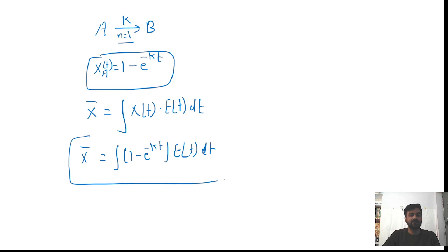The residence time distribution plot will be given, and I will show you in the next lecture with the help of one example. After that you will get to know, and the integral will be from 0 to t. Okay, so you'll have to integrate the thing, and according to that you'll understand the concept. So here it is for a first order reaction, and the residence time plot will be given accordingly, after that you'll calculate the conversion from the segregation model. It's as simple as that.